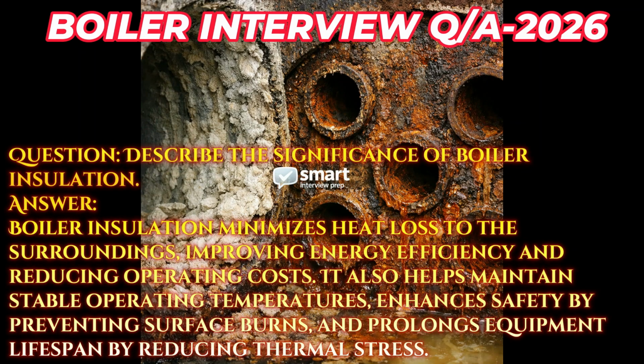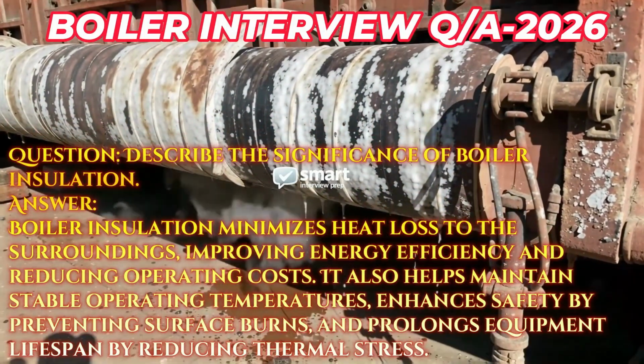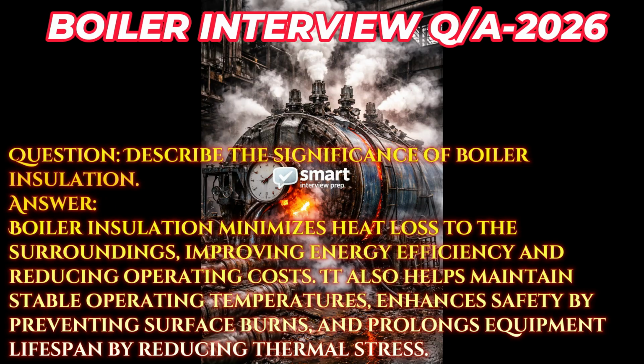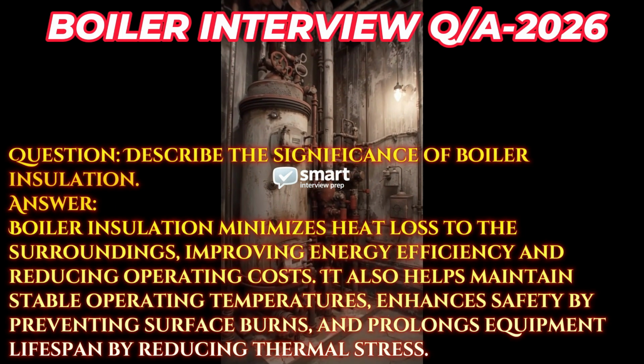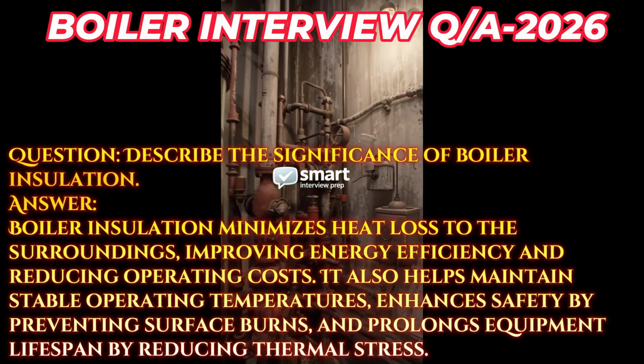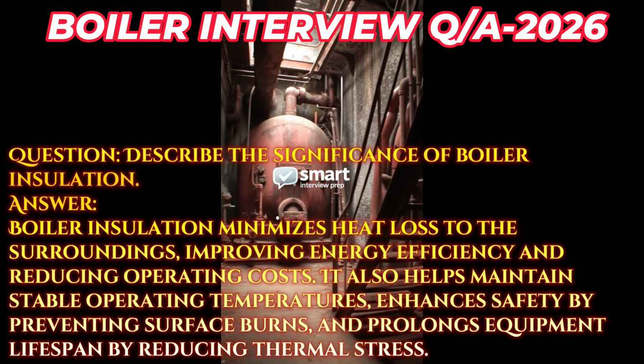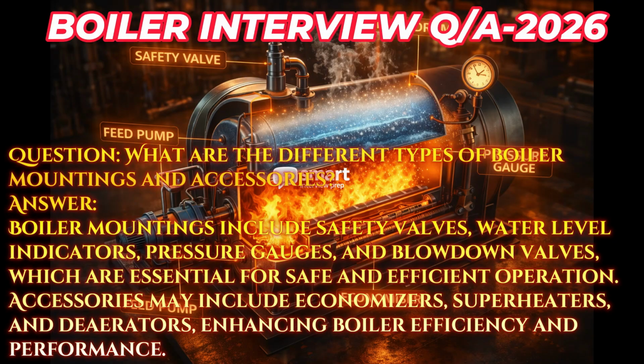Question: describe the significance of boiler insulation. Answer: boiler insulation minimizes heat loss to the surroundings, improving energy efficiency and reducing operating costs. It also helps maintain stable operating temperatures, enhances safety by preventing surface burns, and prolongs equipment lifespan by reducing thermal stress.